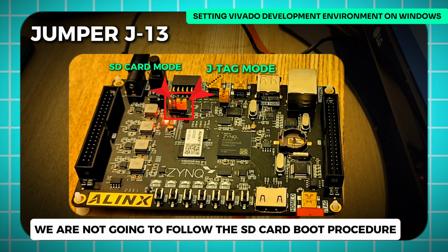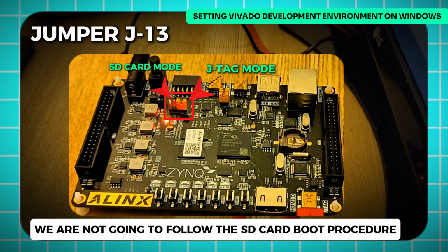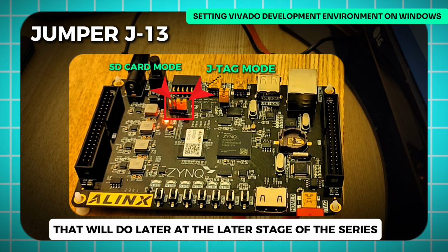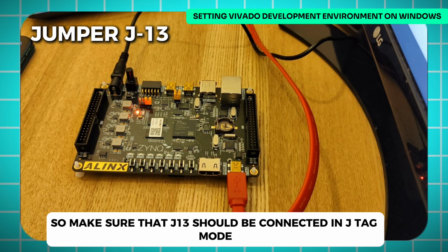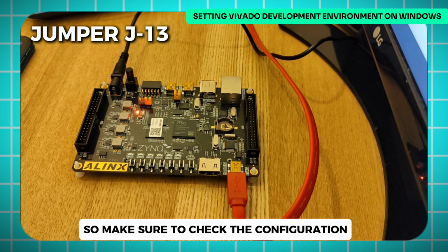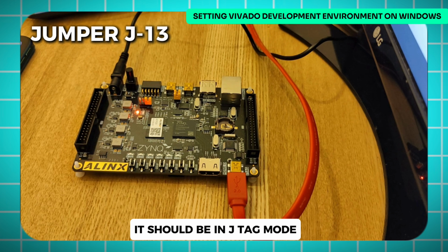Alright, so we are not going to follow the SD card boot procedure as of now. Alright, that we'll do later at a later stage of this series. So make sure that J13 is connected in JTAG mode. If you are using any other development board, make sure to check the configuration. It should be in JTAG mode.